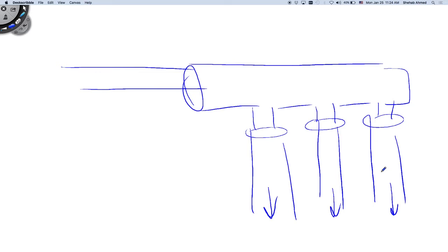And that's why we're always trying to go back and find Vx, the source voltage, because typically the loads are known. You typically know that this process needs a certain flow rate to function. So how do you design the system that makes this process work is what you're working back towards. These are all flow rates that you have defined. They dictate that the flow rate coming in here is equal to the sum of this flow rate plus this flow rate plus this flow rate, right?